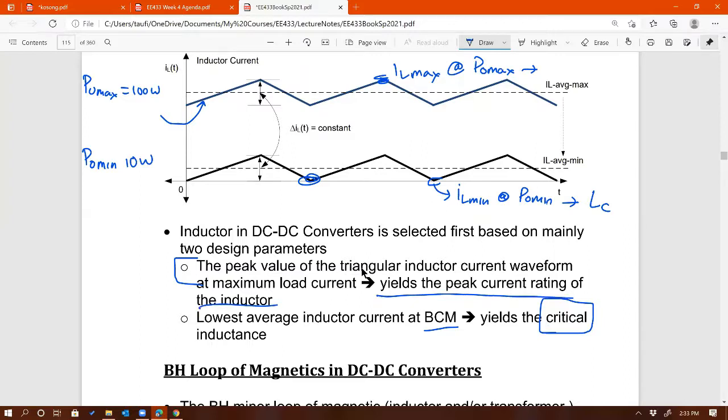So when you buy an inductor, I know you learned already from other classes, let's say from DigiKey or any distributor, what do you need to know before you buy an inductor? Number one, you need to know the inductance value. If you go buy an inductor, you need to know, okay, I want to buy a 10 microhenries inductor, right? You have to know that.